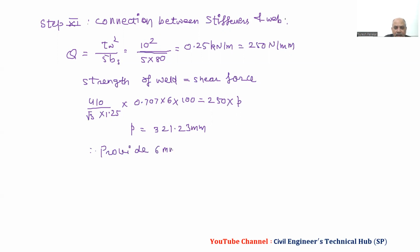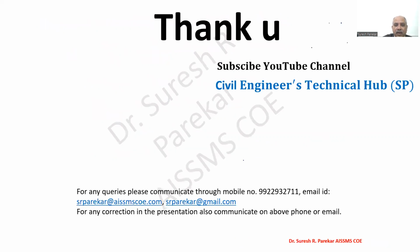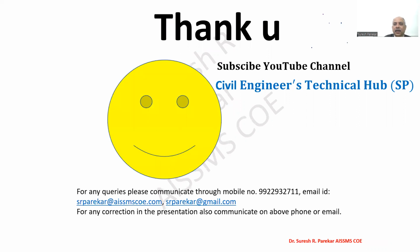And then we can write, therefore, provide 6 millimeter weld of length 100 millimeter at 320 millimeter center to center. And this is all about diagram we have in thumbnail. So this is all about your plate girder. And then we will see in next video, that is unit number 3 problems. So now we will stop here only.